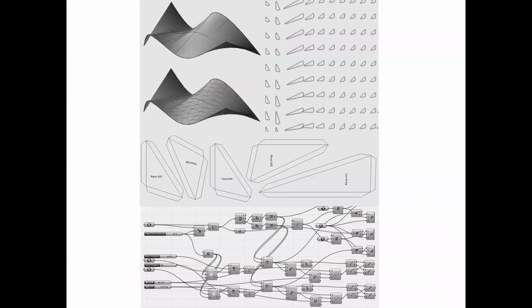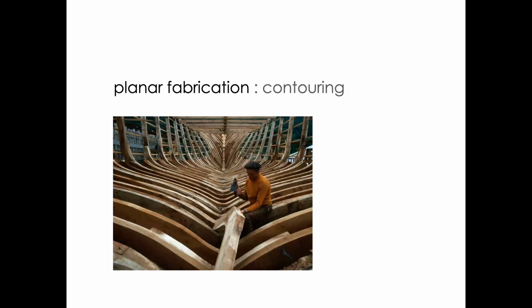Right, so here's another example of taking a surface, breaking it up into components, right? Then taking each of those components, thinking about how they might be assembled, in this case, putting tabs in, then also adding labels and things like that. Since each one's different, each one needs a unique label, so you understand which piece is which, right? Otherwise, you have too complicated of a jigsaw puzzle at the end, you'll never solve it. So let's talk about some of these particular methods that we typically use.